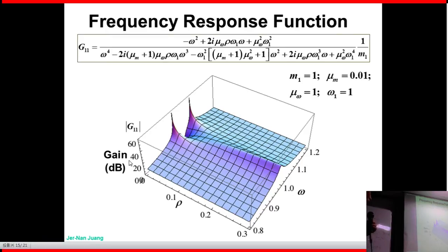Now, if the damping ratio is too low, close to 0, then the system is going to oscillate, that will be no good, right? Agree? However, if you look at that, if the damping ratio is about 0.3, 30%, that's no good either. So the gain here is very large too. And I already showed you.